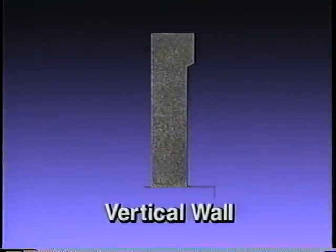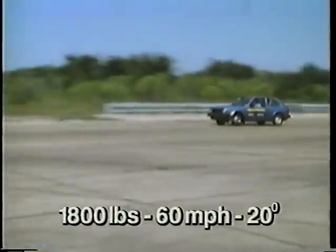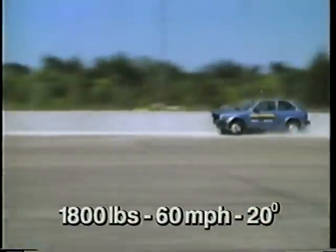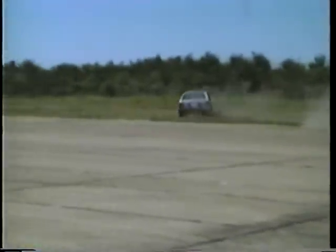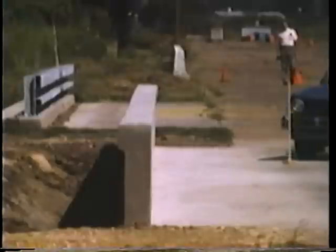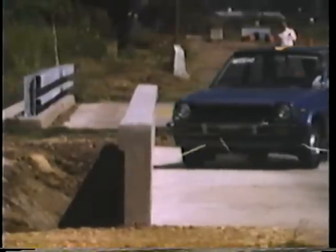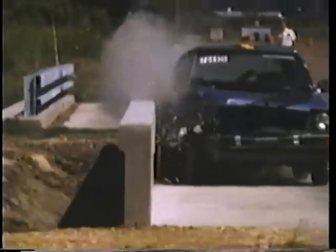Perhaps the most basic bridge rail is a vertical reinforced concrete wall. This simple design is surprisingly effective in containing and redirecting vehicles in a crash without rolling them over. As the shape of the barrier becomes more vertical, the occupant responses become higher than for similar tests with shaped barriers. In the small car test, the lateral occupant impact velocity was essentially at the allowable limit. Although the occupant responses were only barely adequate, the vehicle was much more stable than with either shaped concrete barrier.